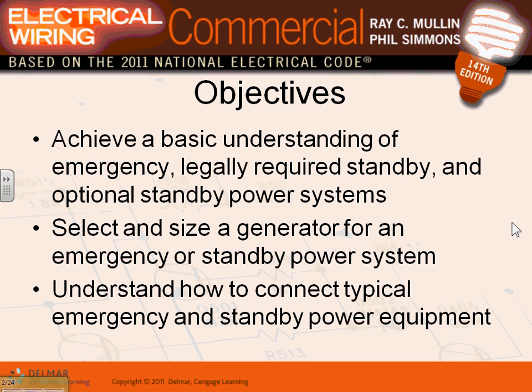Sizing generators for emergency: I'm not going to talk too much about generators. You guys are experts in sizing generators with the software right now. I walked you through the software, and my friend Jerry Buggs also walked you through the software. Really nothing to it other than sizing in two ways: number one, running load, and number two, starting load. We size based on running load and starting load. So that's what we're going to be talking about, guys.